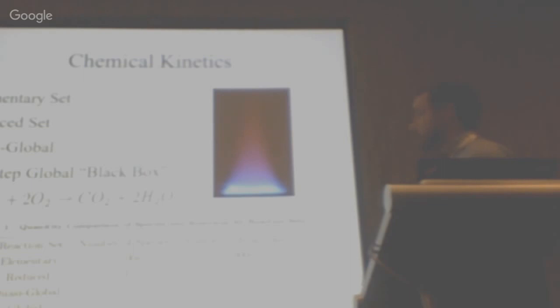The next set, which there's been considerable research into, is a reduced set, where you basically remove everything that is negligible, that you can live without. Right now, there's one for methane, GRI-Mech 3.0. It's 53 species, 325 reactions. Only the most simple 1D cases are usually attempted with this, because you would need 52 additional equations to your traditional set.